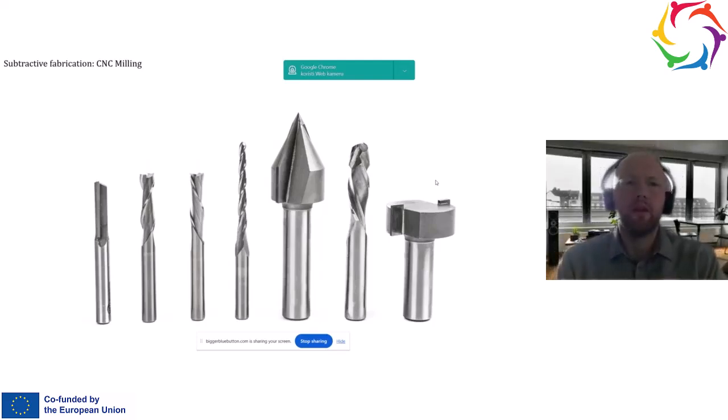What makes the difference between laser cutting and CNC milling is that with CNC milling we can create relief on the facade. So laser cutting and plasma cutting might be interesting if we treat the facade just as a graphical design. So we create two-dimensional drawings and play with that. But if we use CNC milling, we can also play with the relief or depth on the facade or interior design elements.